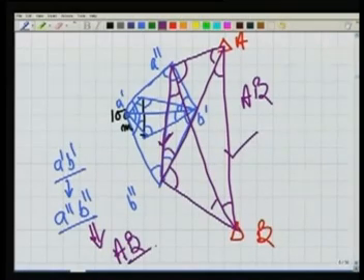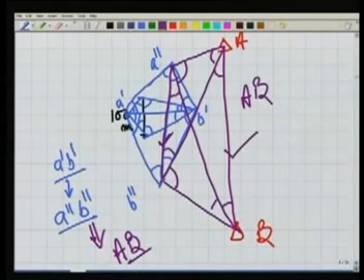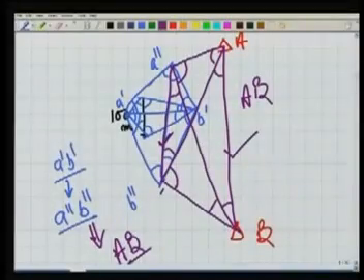So what we saw here, and one more thing, please keep in mind, the moment I say standing at this point B, I am bisecting a point here B dash and a point A dash. What we are doing, we have a ranging rod or something called a signal standing there, and we are bisecting the signal and we are able to measure these angles.